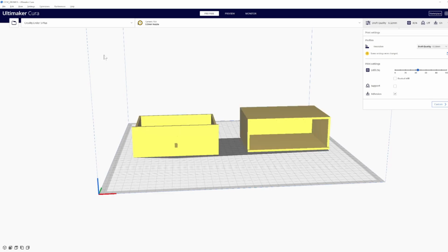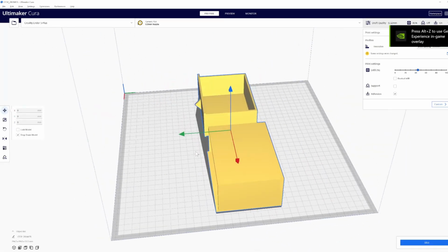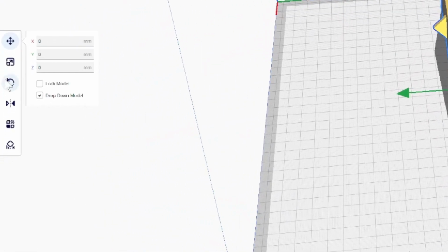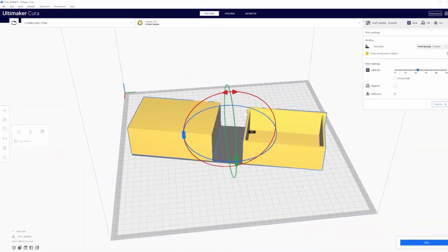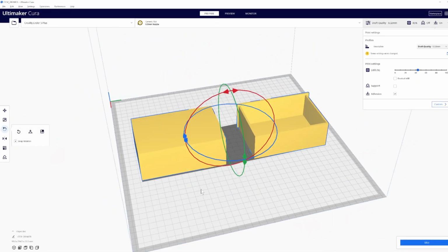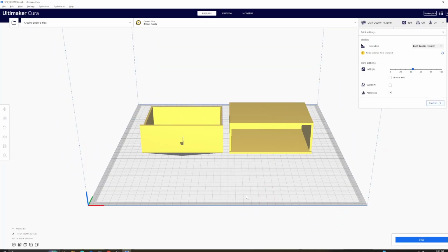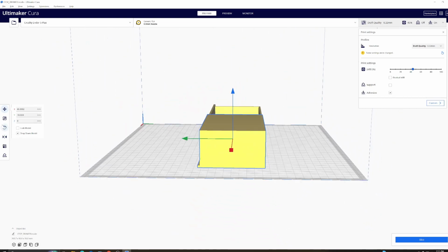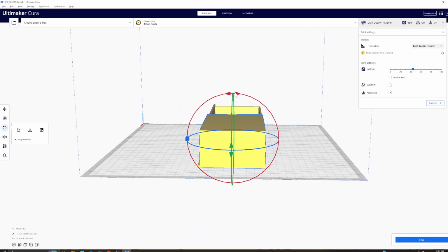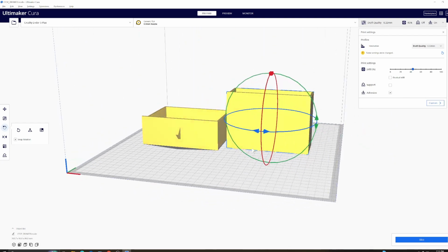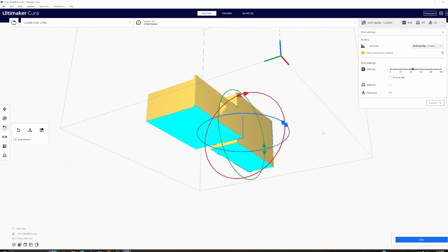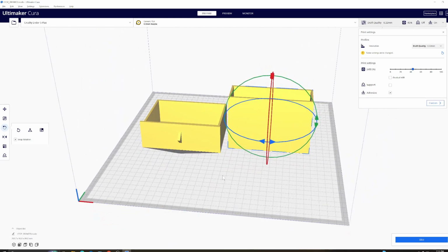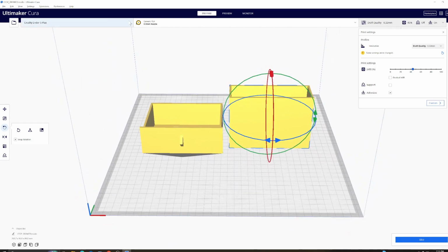Alright, it's opening. See, I can turn this around like this. Or also I could go up here and, ooh, look, I can rotate them. But I just want to rotate just one of the boxes. So let's just select this box. Oh, let's turn this around here. Go over to rotate. Turn this 90 degrees. And watch it pop up. So the reason I turn that 90 degrees is your printer would have a hard time printing. You can't print over air.